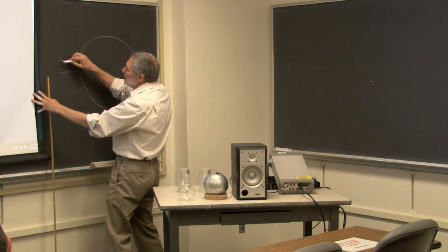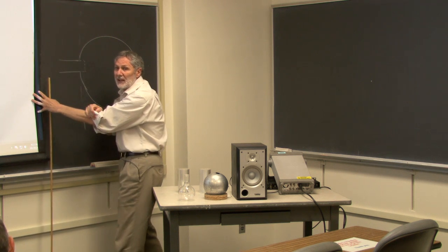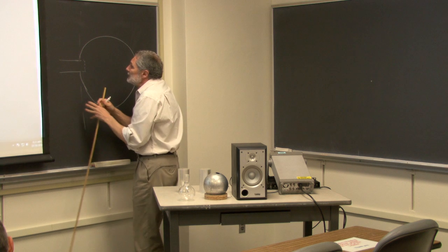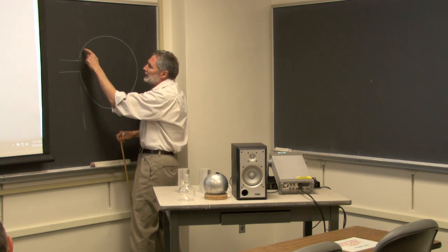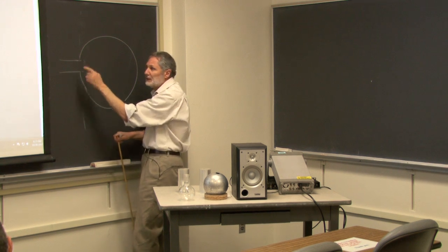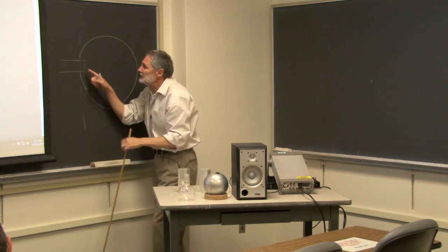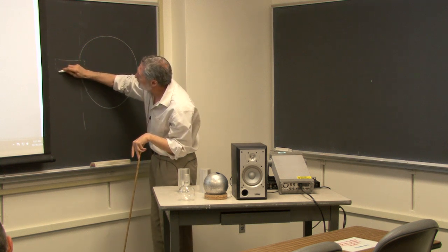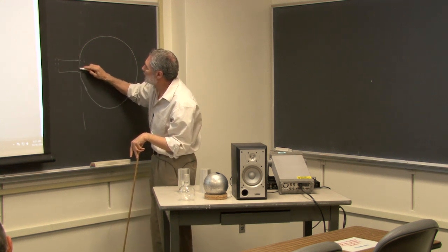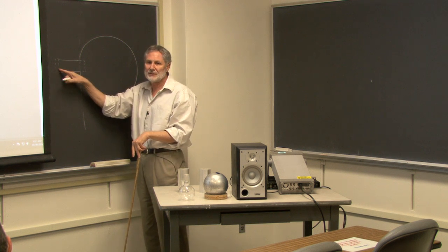Here, the end correction is different because there's no baffle. And the flow here is more confined because of this surface right here. It spreads out more here. So there's greater kinetic energy. There's greater mass here. So that end correction, this end correction is bigger than this end correction.